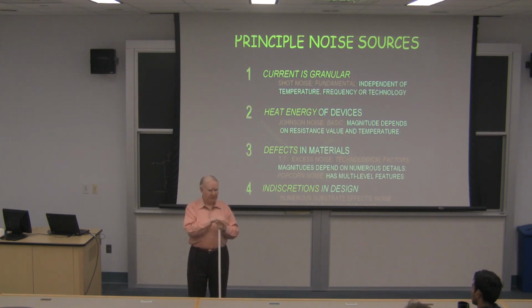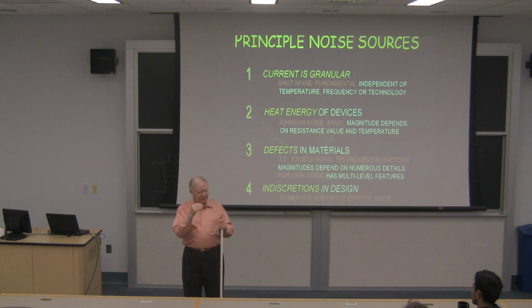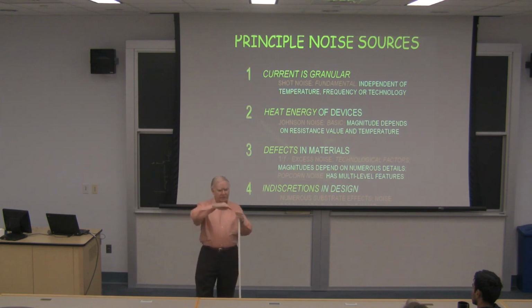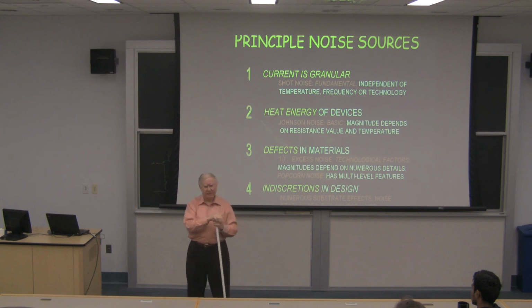If it's a robust design, of course it will vary a little, but what you can often do is optimize the situation so that if there is a hump in the variation, a small hump, you place that at the operating point. In this case, beta F equals 1. Well, I'm sorry, the multiplying factor is equal to 1 for beta F. So I think you can see what I'm saying. Sweep everything generously and really make the circuit get on its knees and confess to its sins. Because if you don't, it'll get away with murder.